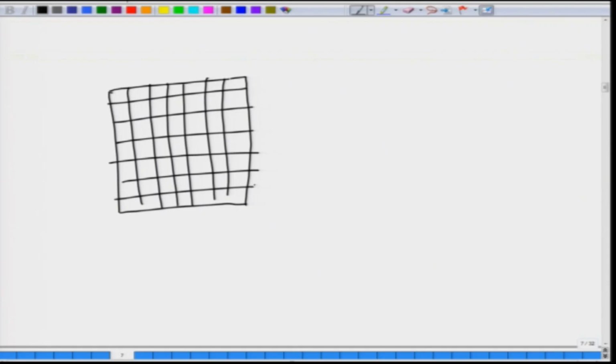So, in the case of every photograph, you will have the R, G and B pixels if you are talking about a true color image. So, let us look at the R pixels. Now, when we have a spot of pixel at this location, how much does this much size correspond to on the ground? So, that gives you an idea of the spatial resolution. So, if you have a greater amount of spatial resolution, you have more pixels in your photograph, so that each pixel corresponds to a smaller area on the ground.